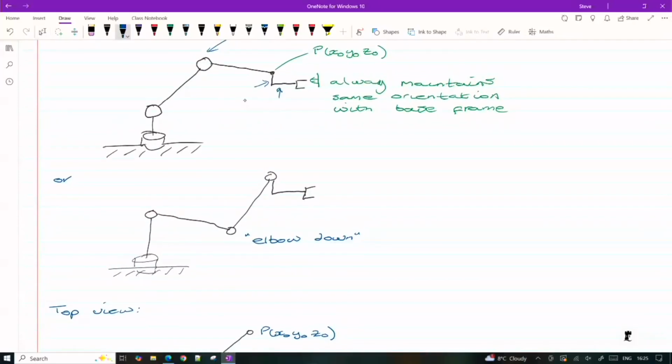What I didn't say is you can treat that end effector as simple offsets to your calculated Px0, Py0, Pz0. Because it always stays in the same position, you don't have to worry about it in your solution per se.